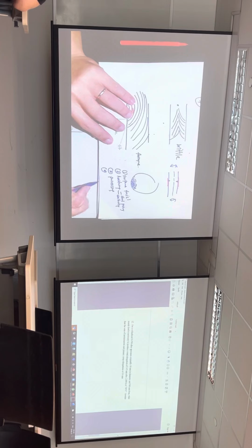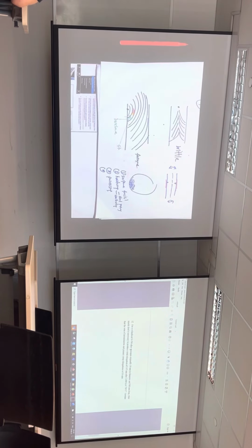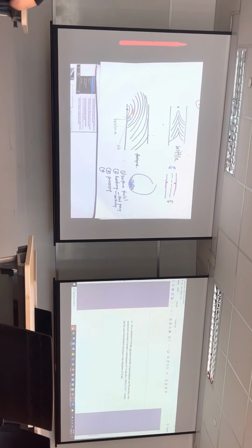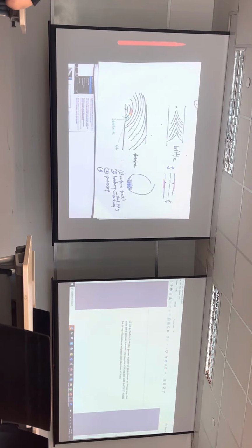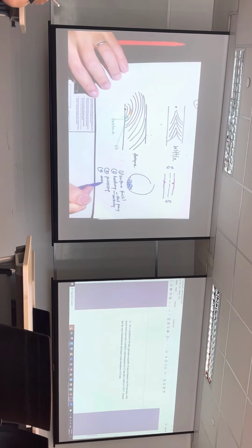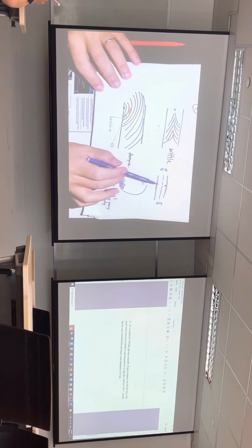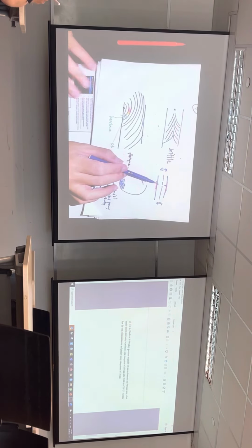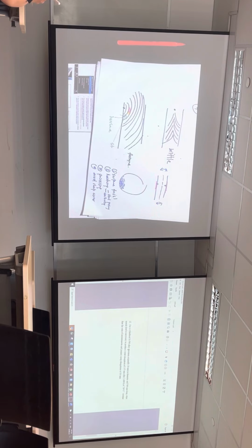Maybe the fourth one I can think of is that you do not design with stress concentrators. Avoid sharp edges and sharp corners in your design. This is what happens if you don't. The moment you have sharp corners, it is almost like an initiation point, and it is always the initiation point for failure. Does it make sense? Yes. Okay, so simple.